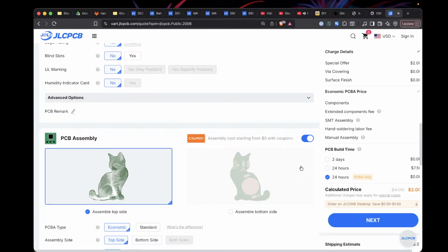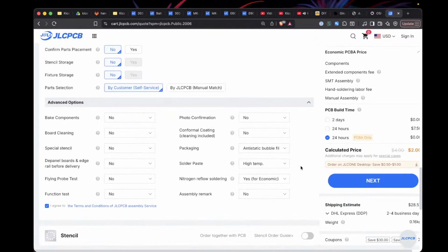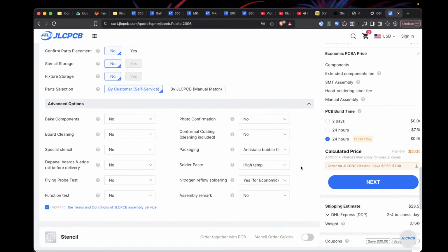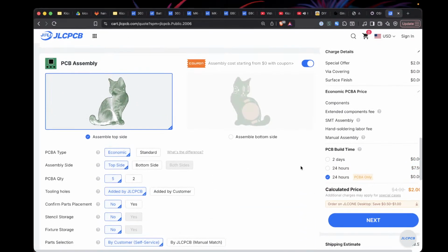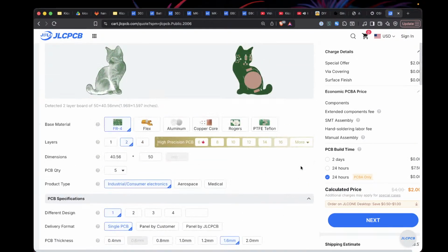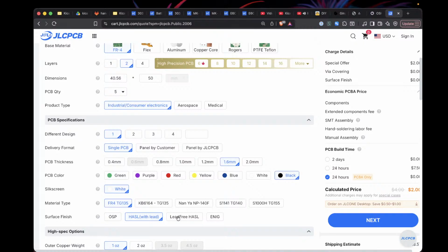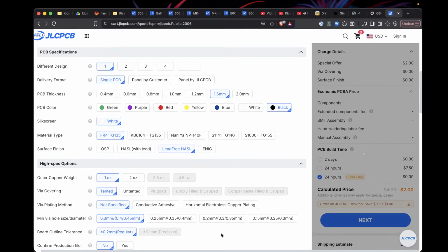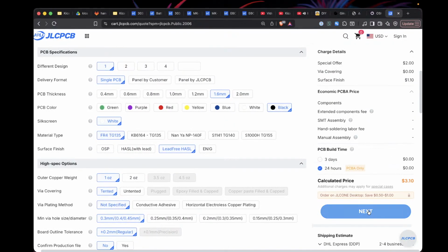Yeah. So this is a board of mine that I've ordered on JLC PCB, and so the circuit board is just, you get a circuit board like this. And then the PCB assembly is a separate thing where I've uploaded a list of all of the parts with the part numbers on LCSC. So they'll source all of these parts, they'll buy them, or they'll ship them over from their other warehouse, and then they'll place them down on the device. So this is like a diagram of every single part and where it would go. And they'll actually have their pick and place robot put it all down.